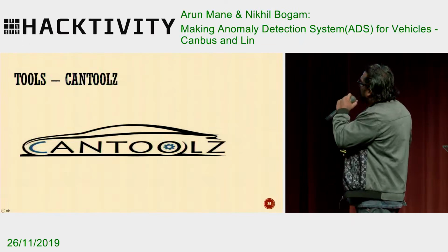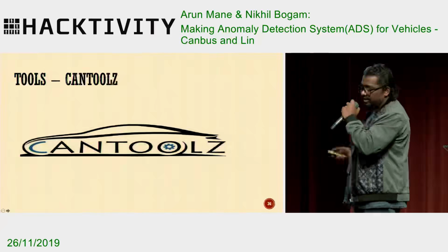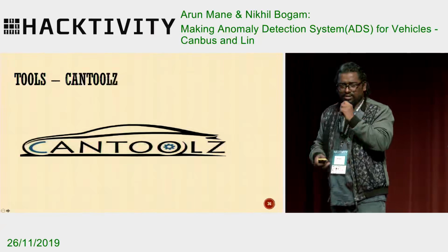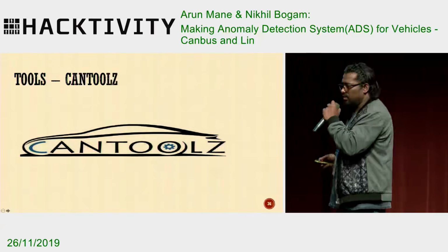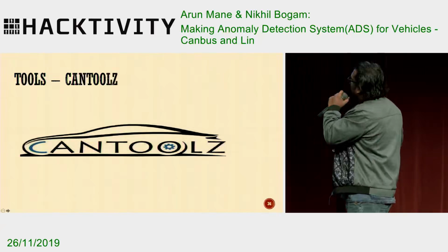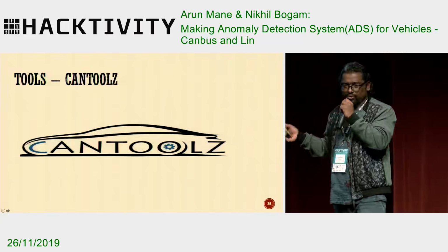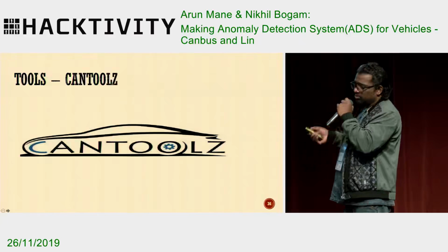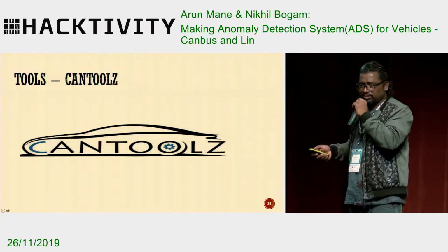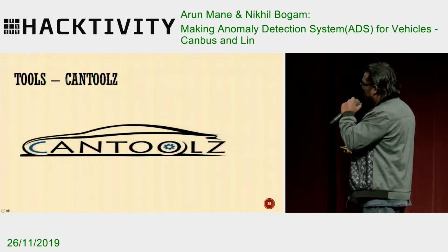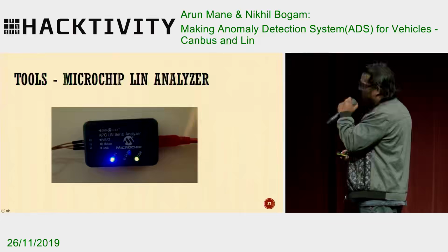CAN Tools, again, the Russian guys made a very nice tool. It's written in Python, with Qt and the Python programming language. And it supports USBtin, CANtact, and a lot of open source tools you can use. It's based on the can-utils Linux utility, and it's a very nice tool, and you can use it for fuzzing as well.